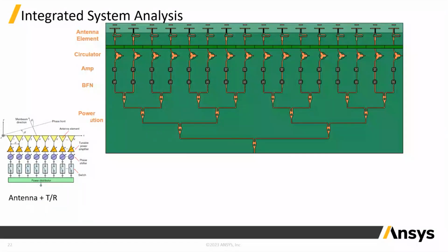Okay, so coming to 5G, 5G is very much in demand now with the higher data rate requirement, and you need to use higher and higher frequencies. In order to mitigate the losses generated because of the distance in fixed transmission, you need to use arrays of antennas in order to steer the beam to left and right.